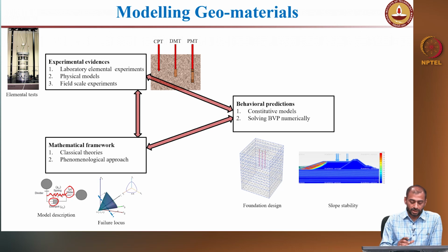So you have a mathematical framework set, and from the experimental evidence you have a mathematical framework. Now using these tools, you try to formulate a constitutive model relating the stresses and strains. Once you relate these stresses and strains, you come up with a framework to model the response. That will be built into a numerical scheme, which I will be showing in the next slide, and you will try to solve any boundary value problem.